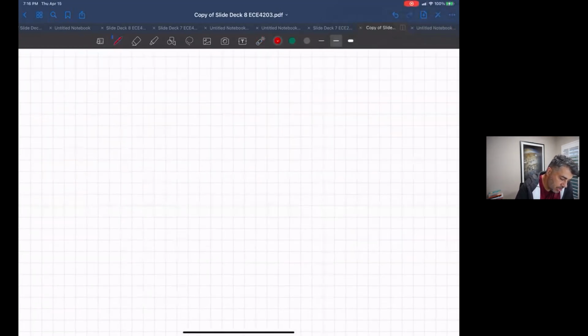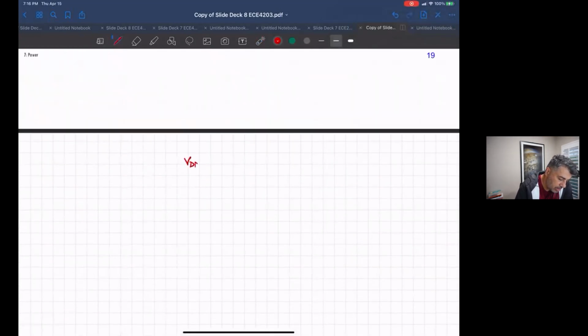Let's say you have a VDD low and a VDD high. For the sake of discussion, VDD high is 1.8 volts and VDD low is 1.2 volts. It's not that uncommon. One thing you want to do is make sure those are well separated; you don't want them physically in a jumble because they're hard to keep track of.